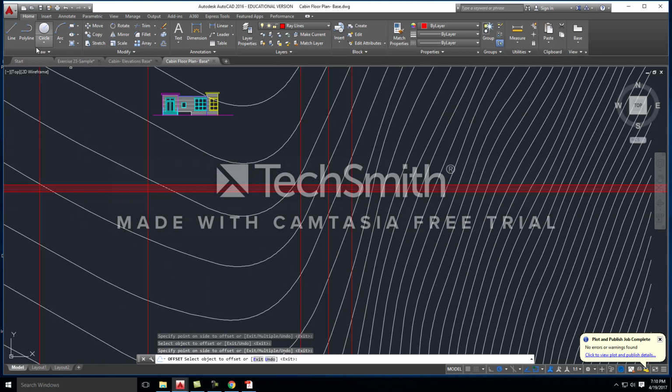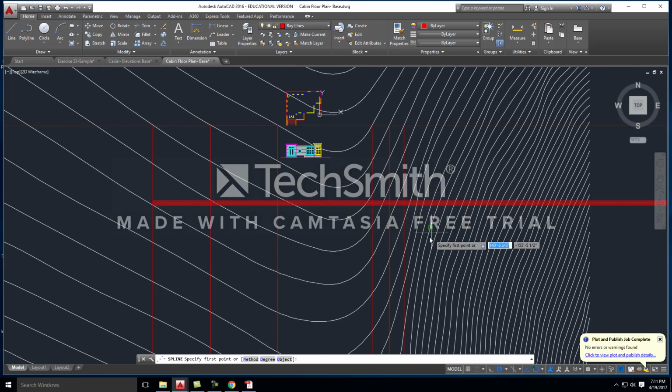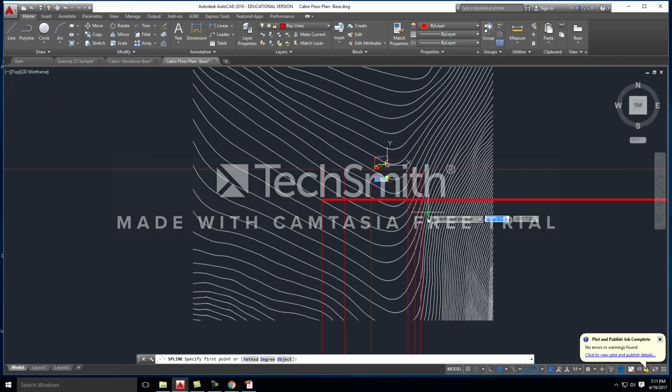And then from there, we're going to go up to where it says draw, and click on that little drop down menu, and we're going to use a tool that we haven't learned yet, and that's going to be a spline. So we're going to click on spline CV, spline curve. And we're going to click on that point, and start at where the first line is, given that we're actually going uphill here. Remember that our river is running right through this point, and the grades are traveling upwards. And it's also going uphill going this way.